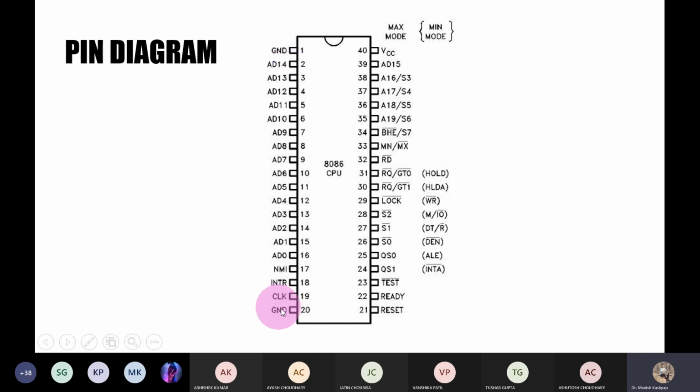So that is why they have attached two ground pins here, right? So that the load of this will be half and the load of this will be half. The technical specifications of this IC are that it will have a plus 5 volt DC supply and two ground voltages, right? And unlike in 8085, where we had two inputs for crystal oscillator X1 and X2, here you do not have any inputs for crystal oscillator X1 and X2.